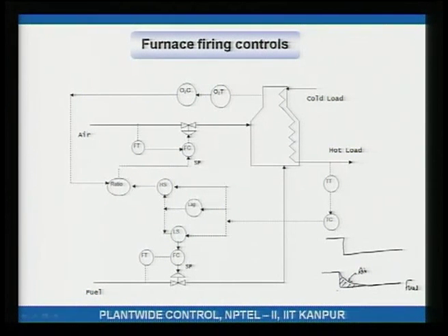During that transient period, you are getting air rich regime, you have extra air than fuel, right. This extra air than fuel ensures that whatever fuel enters the furnace, it gets burnt away, none of it remains, and it is absolutely essential to ensure this, because any unburnt fuel may lead to a disaster next time the furnace is started.